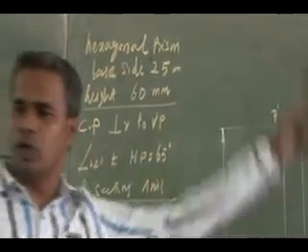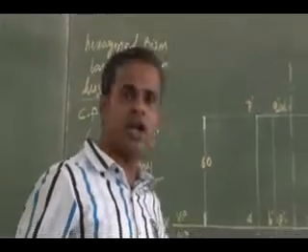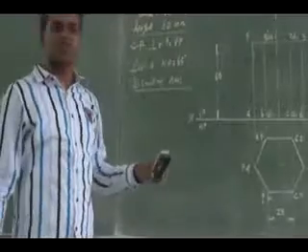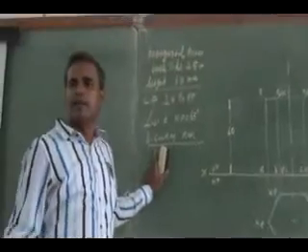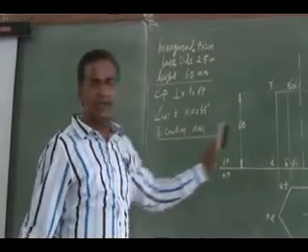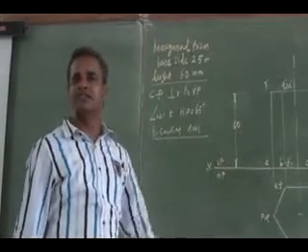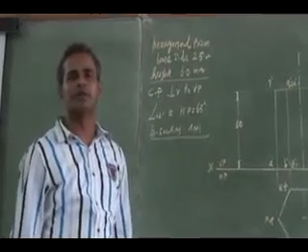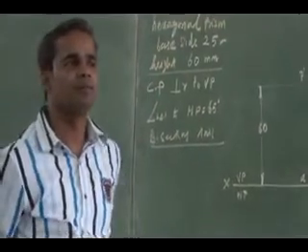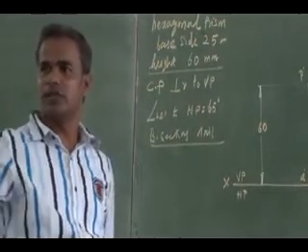Now can you show the cutting plane, mark the cutting points, rotate the cutting points and the fixed plane to 65 degrees to HP by bisecting the axis, right? You need not draw the sectional top view. Draw the lateral surface development of the retained portion of the hexagon. Okay, that is the problem.